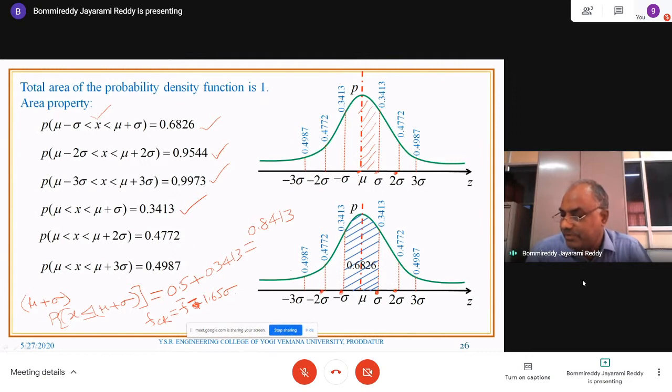So what is the meaning here? This area must be 5%. Characteristic strength means the strength of the material below which not more than 5% of the test results are expected to fall. So corresponding to 5%, the K value is 1.65 sigma. So F bar minus 1.65 sigma. In that way you can compute the characteristic strength of the concrete. I will discuss this a little later.